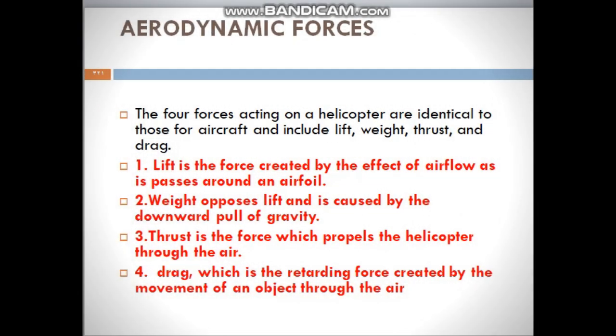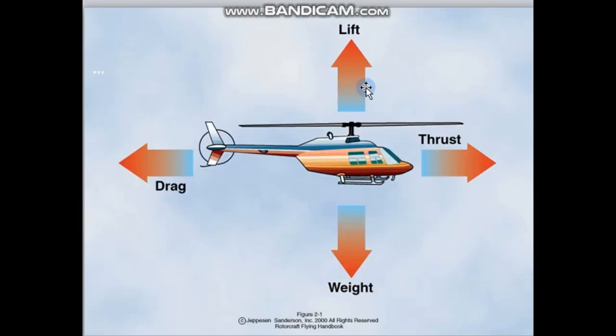Aerodynamic forces. The four forces acting on the helicopter are identical to those for aircraft and include lift, weight, thrust, and drag. The lift is the force created by the effect of airflow as it passes around the airfoil. As we see in this figure, this is the lift.